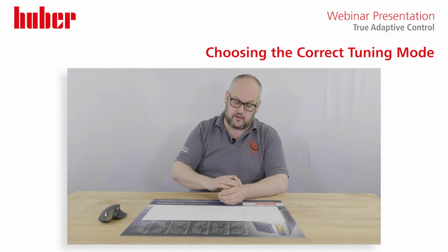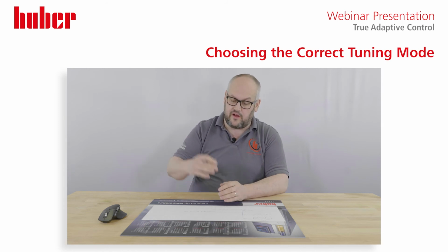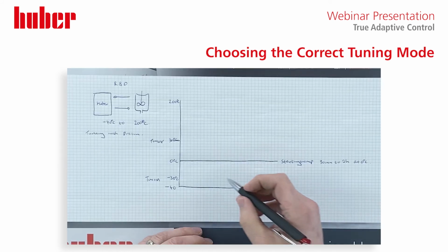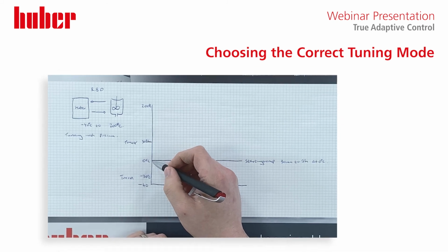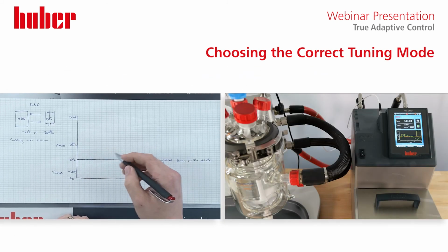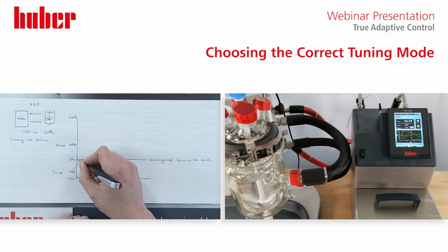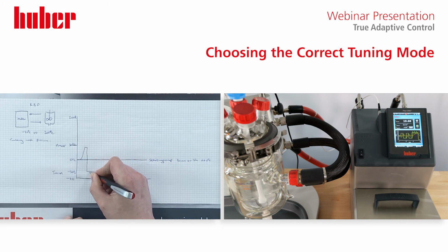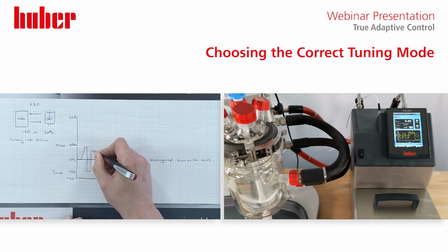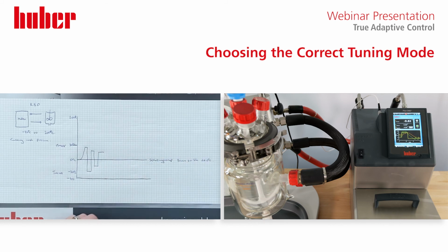And then it will start looking at heating up and cooling down, how fast it can do it, and will it overshoot. So what you often see, as you'll see in the time lapse we'll show here of tuning with preliminary testing, the unit will often apply heat, it will then change its set point, hold, drop down, go up, and it will just scope its way out through the system.